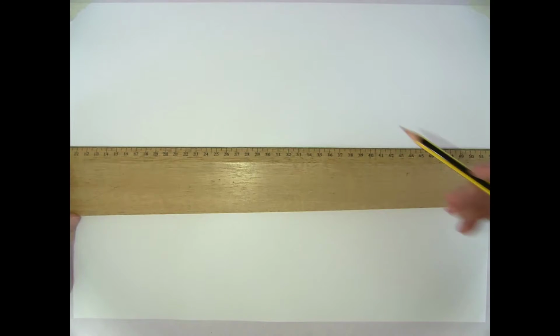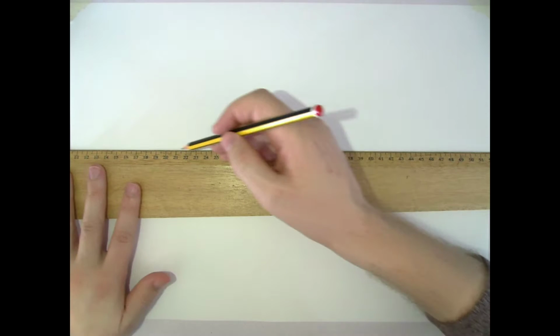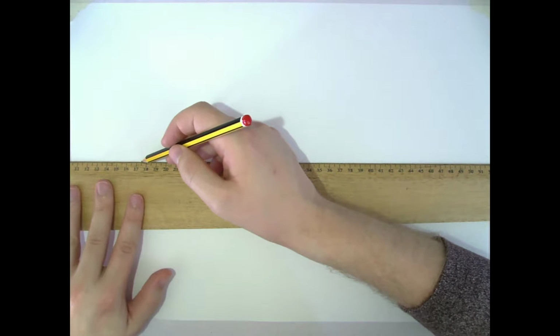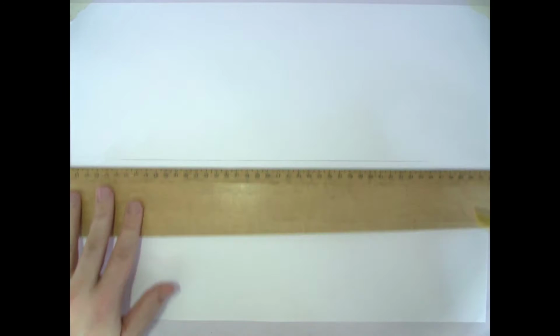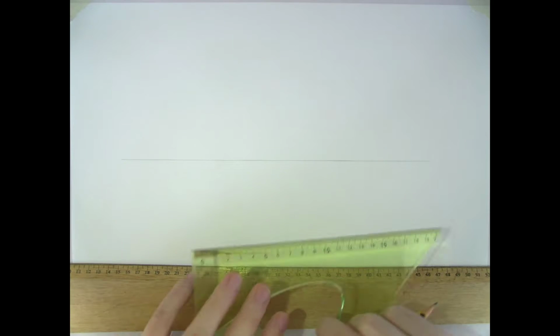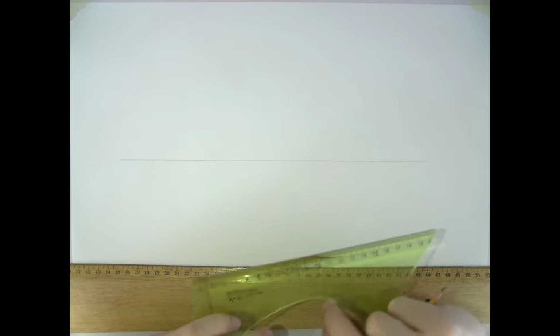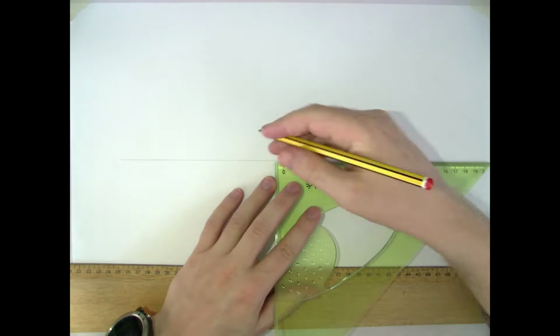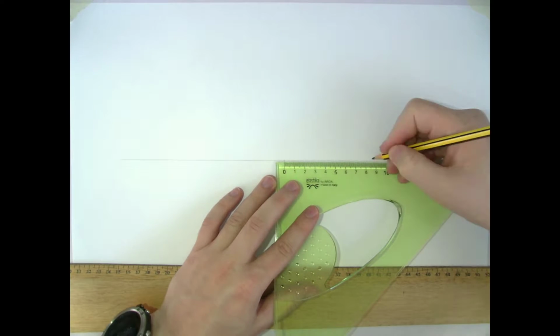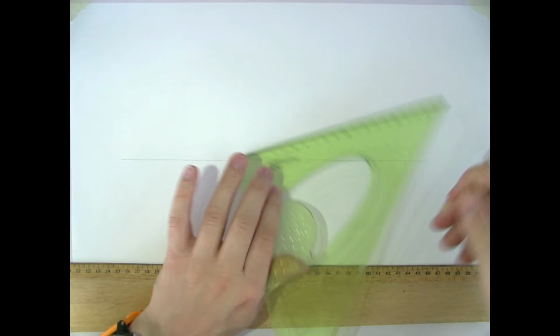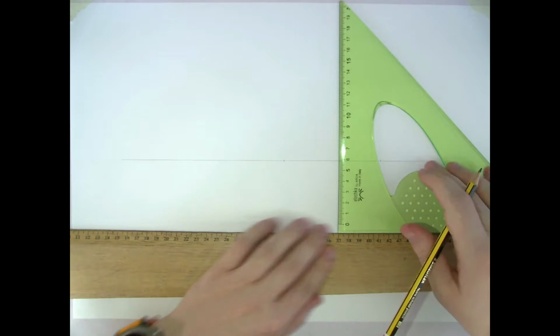So with all of the questions that I do for orthographic, I like to set them up in boxes first, so that it's clear that everything is going to fit on my page. The width of the elevation is going to be 80 millimeters plus 15, so 95 millimeters. So I'm going to create a box that's 95 millimeters wide, and it has a height of 60.